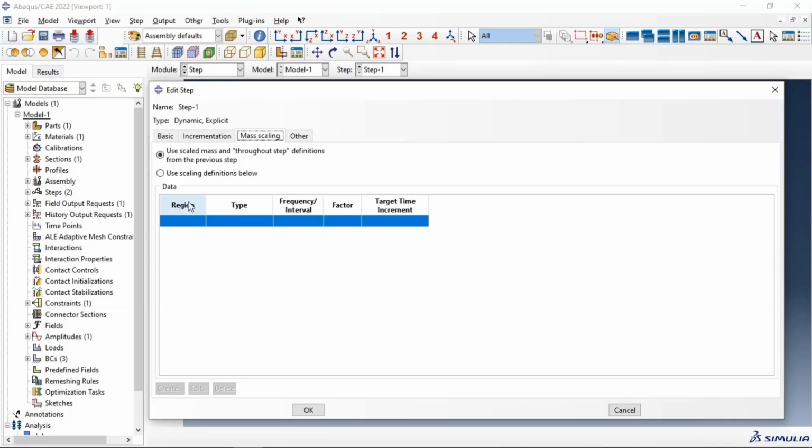These outputs will help in the post processing and evaluating the structural response. Now I'll generate a mesh. I'll create a mesh by assigning the element type. For a 3D solid concrete model, I'll use reduced integration brick elements because these are commonly preferred.